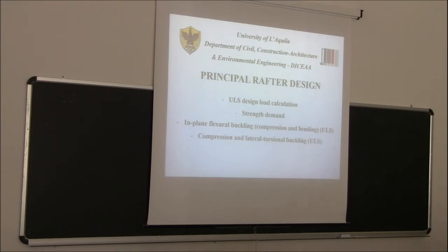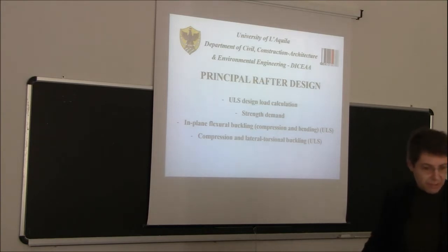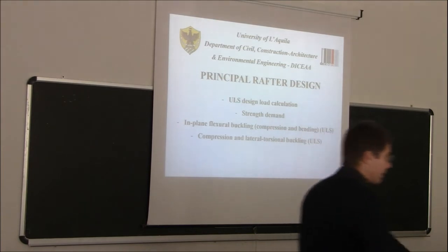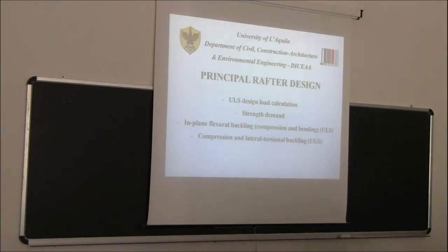Okay? So as you can see, when we talk about timber but also steel, we are very concerned about buckling, about stability basically. So we always have to check the in-plane buckling and then the out-of-plane buckling. And again, we have to make some assumptions about restraints.